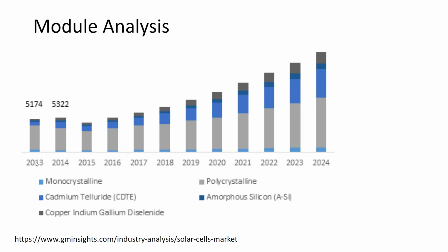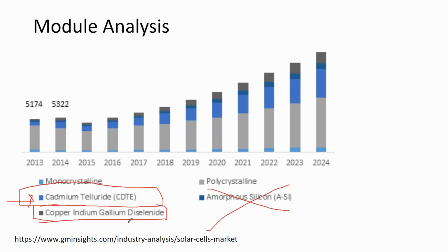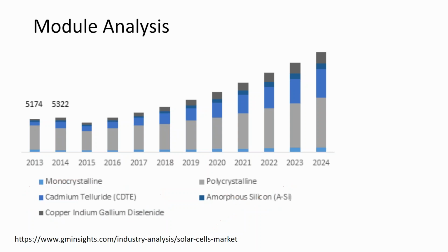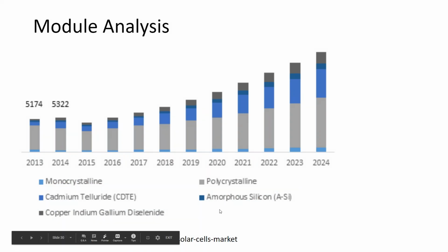And then all the other thin film technologies have pretty much made their way out of the market. I rarely see any amorphous silicon. Sometimes it's talked about being put on top of existing solar because it's kind of translucent, to boost production. There is a U.S. manufacturer called First Solar that's the exception to the rule, and they make their own solar panels not using silicon. But their materials are not as environmentally friendly as silicon, and so they're better put in a utility scale project rather than up on a rooftop that could burn down and leach bad metals into the ground. There is a manufacturer making copper, indium, gallium, selenium modules called Solar Frontier, but by and large, their competitors have exited the market. So silicon is pretty much where it's at.